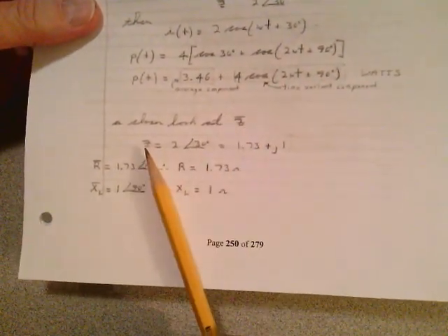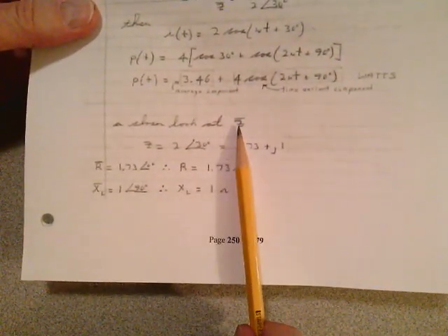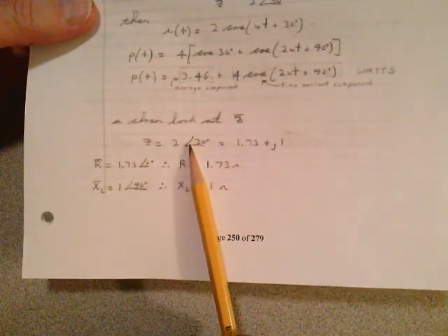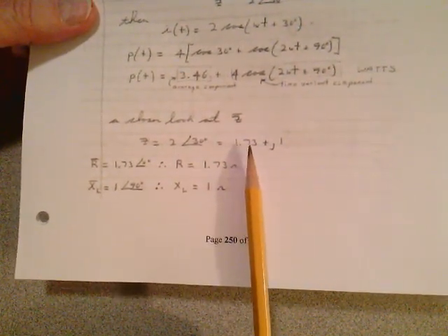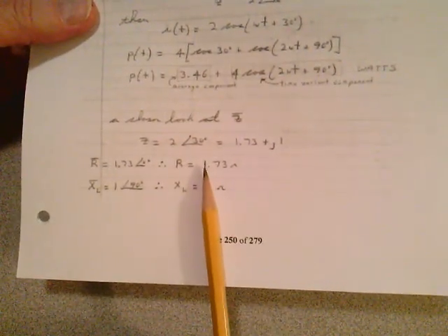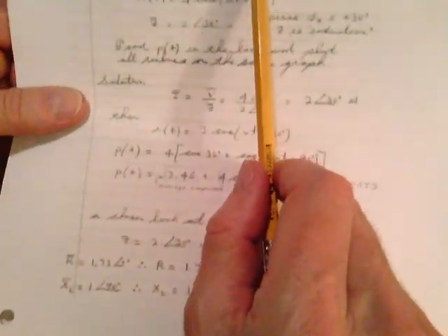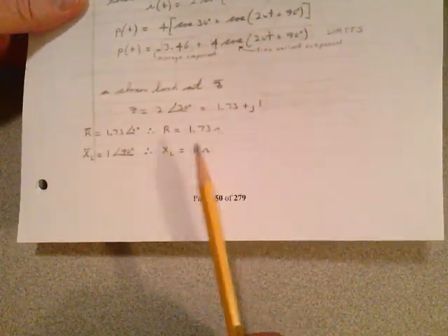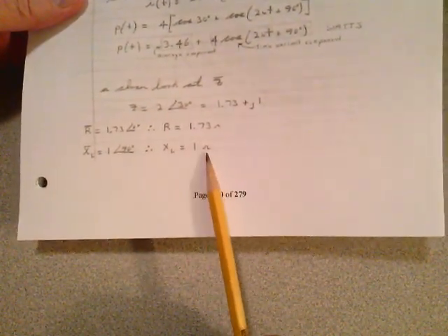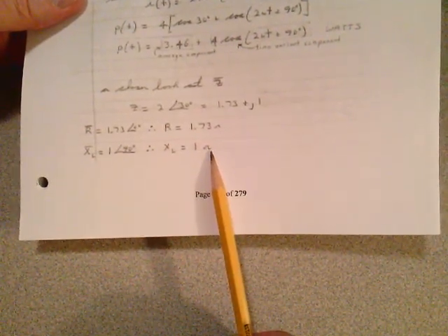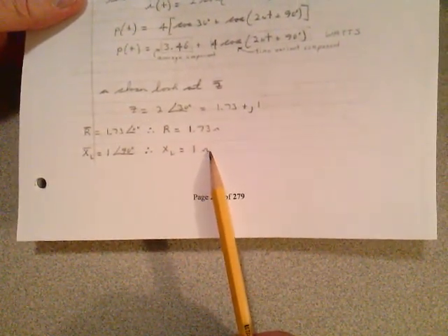Instantaneously, a closer look at this, just in mentioning the impedance, we know that's the polar form of the impedance that we found up above. You get back to rectangular form, it's 1.73 plus j1, so that means the real part of the resistors in that box up above is 1.73 ohms, and the inductive reactance is 1 ohm, which would be shown as a plus j1 if you're looking at it in terms of a vector quantity.